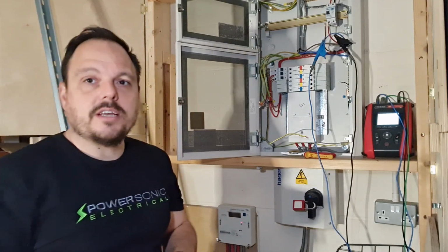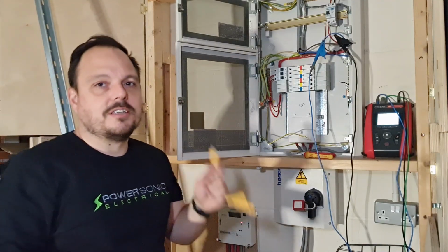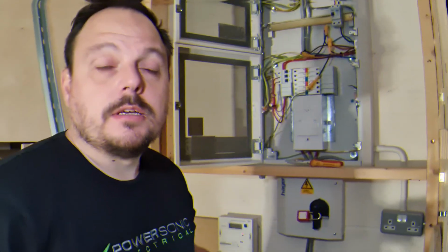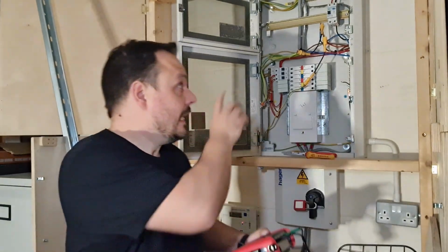And then we'll jump up and get an R1, R2 on the lighting circuit, get all this lot dressed back away, and we can take our live measurements. So I'll just jump these over now and I'll show you me getting the R1, R2s. Okay, so I've got that all jumped over now.